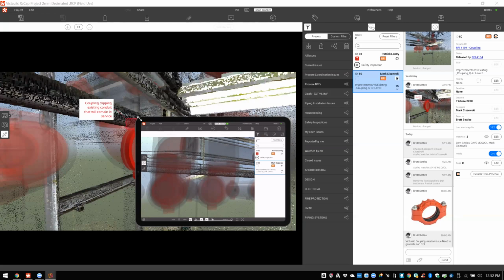The other one was about RFIs and Procore. Please show more about the life cycle of an RFI in Procore. Can you track it inside Procore if it's solved or not? Absolutely. So in the RFI module, you'll see there's an exhaustive change history that lets you know. You can also see there's commenting so that the designers can comment back and forth, and actions that you can take, so you can track that RFI, every event, every detail that's happening.